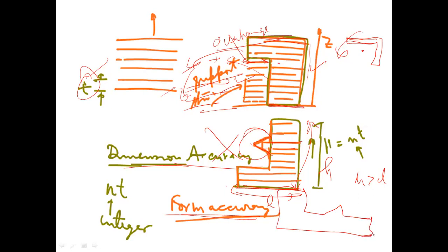So you cannot balance out the minimum area and the critical feature criteria. So now you have taken the maximum contact area in support. So what is recommended is that if this is h, then h plus 2 mm will actually help you to get the accurate part. So all these decisions have to be made during the pre-processing of the CAD model, while you are working with the CAD model.